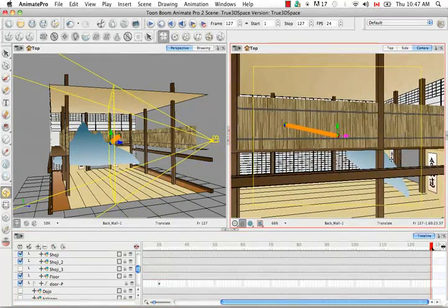So from here you're starting to see a pretty crazy distortion. This doesn't look like our mountain here. It is really starting to look like a flattened piece of paper. So what we're going to do is add an ortho lock to our mountain.